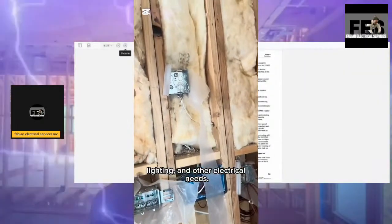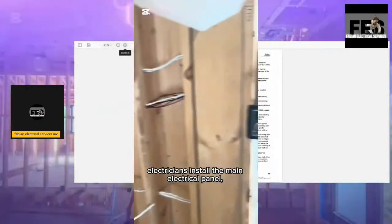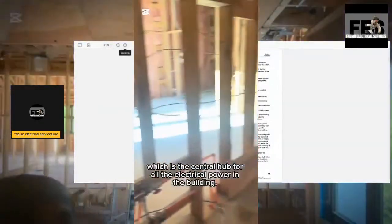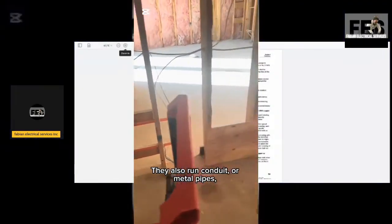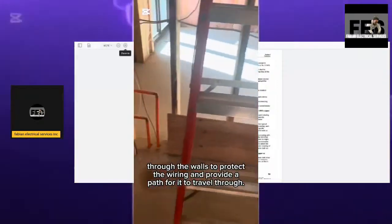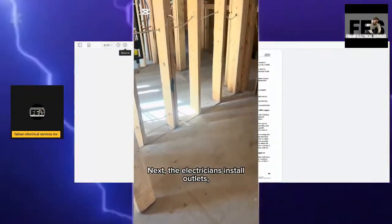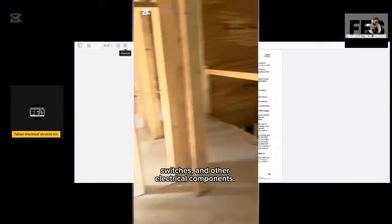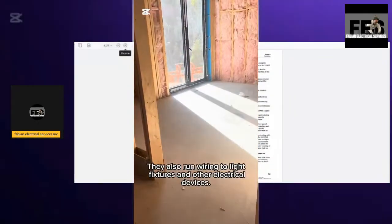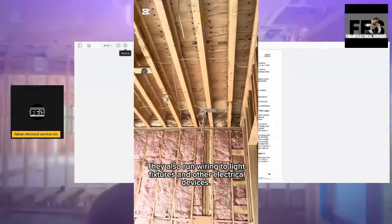So in today's video, what we have is simply a rough-in that was done throughout the home. This is basically a walkthrough of the rough-in before finishing, before the drywall goes up. As you can see, all my wires are neatly strapped. When it comes to my wires going through the 2x8, they are dead in the center. There's a code rule on that also.